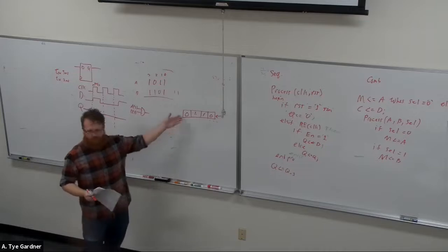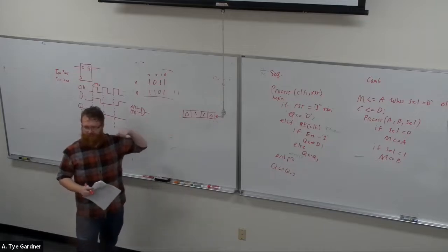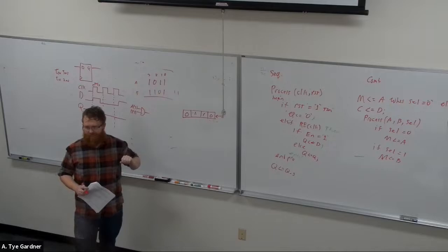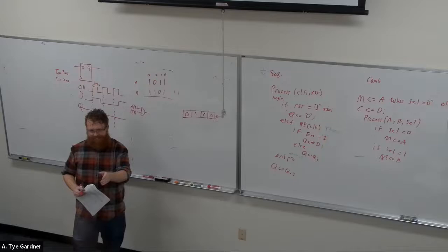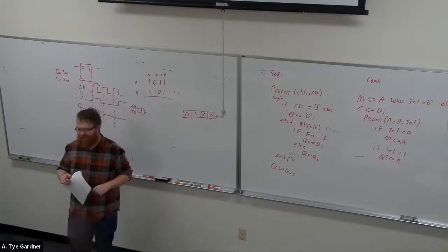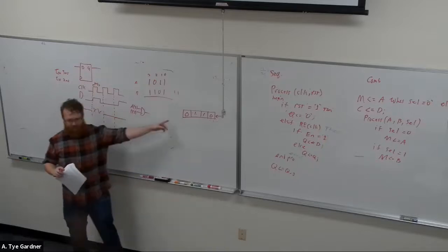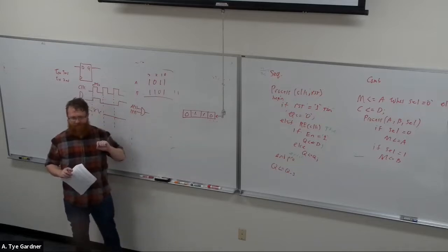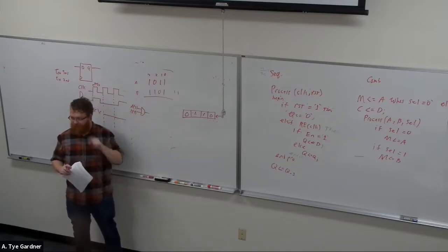In fact, how would you design the shift register? What would be your basic element? Yes, you can do it with a mux. Yeah, this actually does work just fine with a mux. This also works just fine with the flip-flops. With the flip-flops, it can only shift once per cycle.